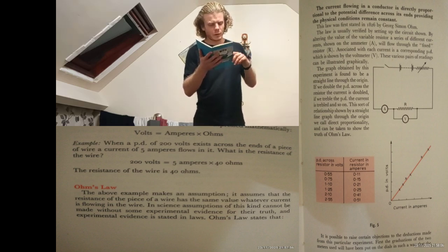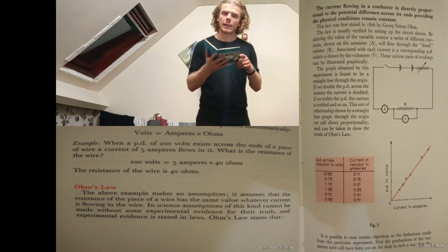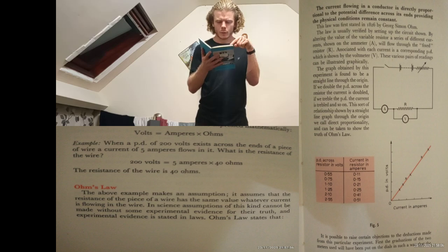When a current flows through, it will change its resistance considerably in so doing. Typical values for a domestic lamp would be a cold resistance of 40 ohms and a hot resistance of 450 ohms. That means that it is way hotter, and now it has much more resistance.